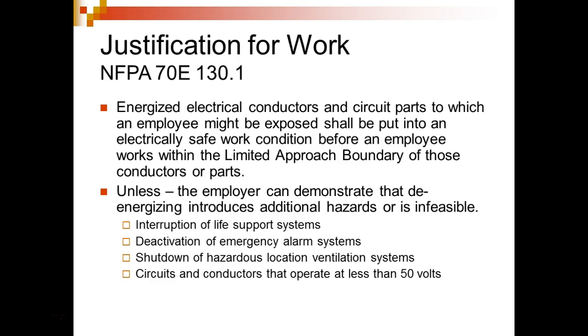You understand that? So this guy here is most of the time what we measure, and you can measure the input resistance of your meter. You can just take another meter and put it on ohms, right? You understand? And then hook it across this one, which is on volts. And you can measure the resistance of this meter. This meter usually measures around 11 megohms.